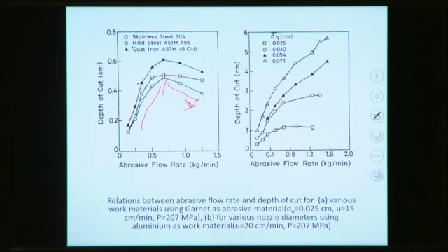Okay, so here also you can see if we increase the abrasive flow rate, your depth of cut also increases. But one interesting thing here is that the depth of cut increases with increasing nozzle diameter. Here the nozzle diameter is 0.25 centimeter, but in this case the nozzle diameter is 0.701 centimeter. So with the increase in nozzle diameter, your depth of cut also increases.